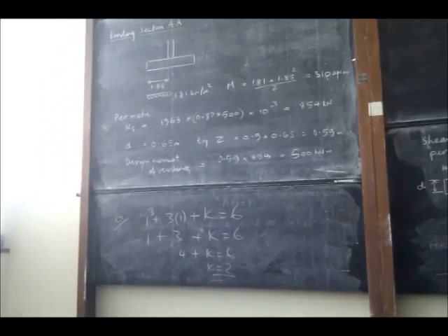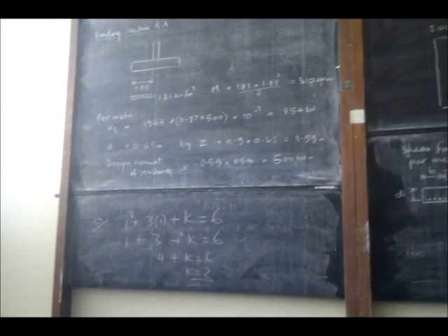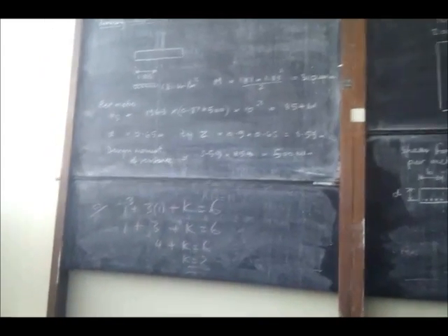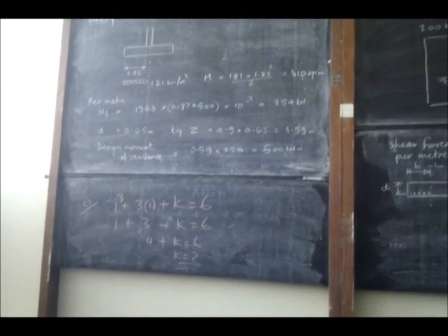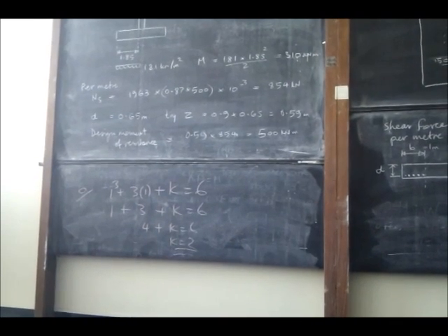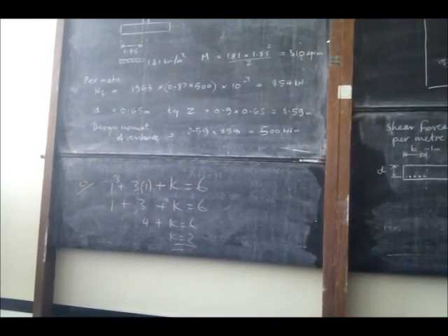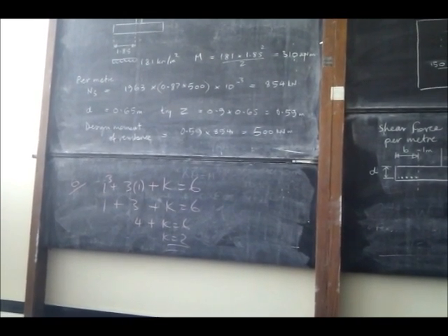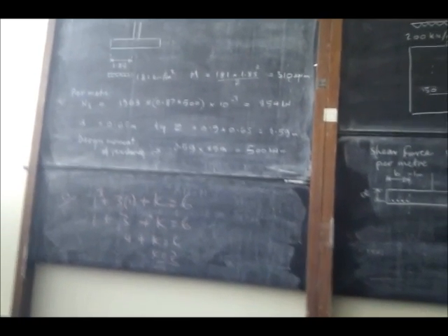Can you just say again how you chose 0.9 for Z? Z's got to be between 0.82 and 0.95. 0.82 is the lower limit for an under-reinforced section. Any less than that, we can't go because the reinforcement may not yield. That'd be the case for single reinforced only, would it? Yeah, because for double reinforced, yeah. Your alternative is to use the formula in the data sheet in this particular example if you want to.